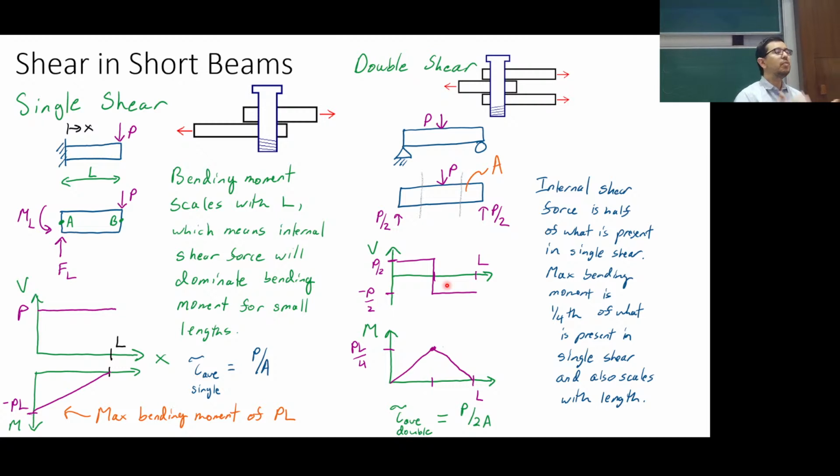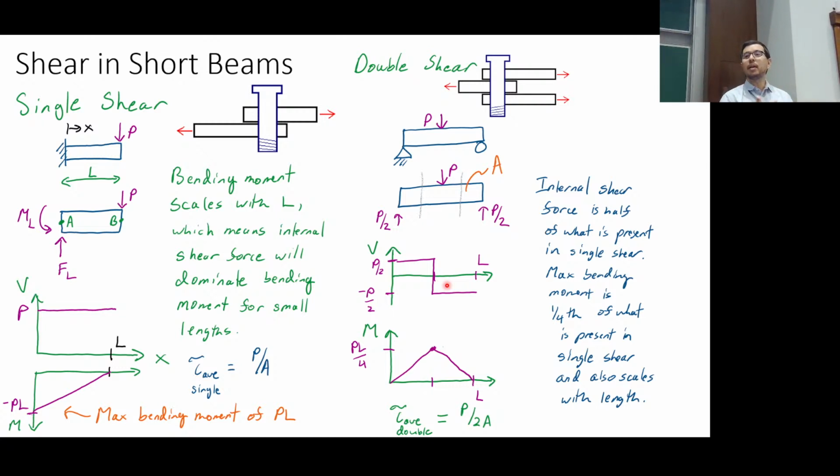But before you even get to that point, you can do some back of the envelope calculations or think in your head: is this device going to fail because of shear? Is it going to fail because of bending moments? Or because of a combination of things? Is it a rod that's twisting, where I'm going to have issues with shear? Is it a bar? Is it one of these pin configurations?